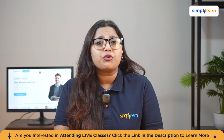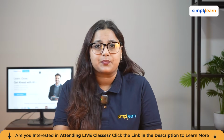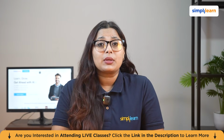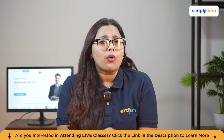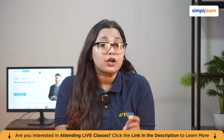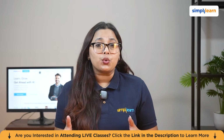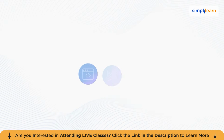And you will also know how to create a custom work week configuration for 6 working days. You will understand how to assign a different calendar to different tasks, critical when subcontractors have different working hours. And you will know how to use task constraints correctly and, crucially, when not to use them, because over-constraining a schedule is one of the most common planning mistakes in the industry.